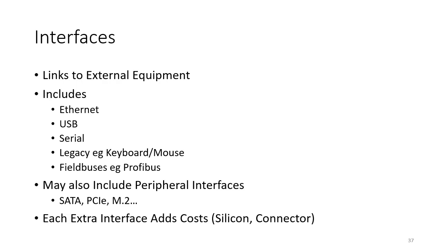So commonly in an industrial PC, you'll find USB connections, which can have multiple uses, and it doesn't really add too much cost to have a few more USBs than you might need. Ethernet, again, the cost of adding an Ethernet connector along with a switch, it might be internal to the industrial PC, so it needs some real estate on the board, but the actual amount of electronics and the amount of connector technology, it's minimal. If you really wanted to save every cent or every penny, then you might be concerned with minimizing the number of interfaces.